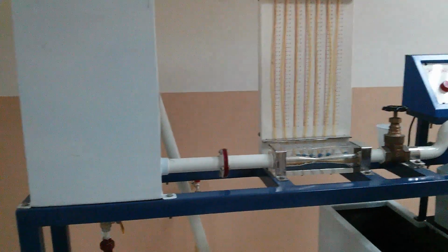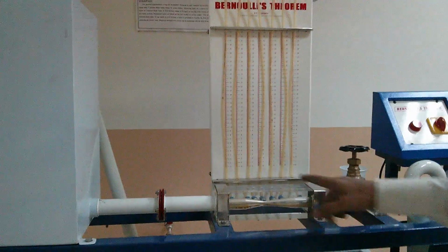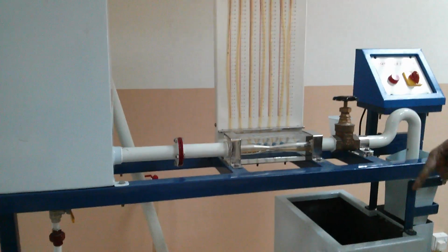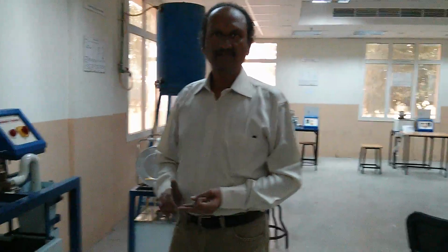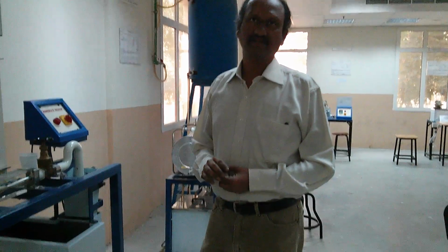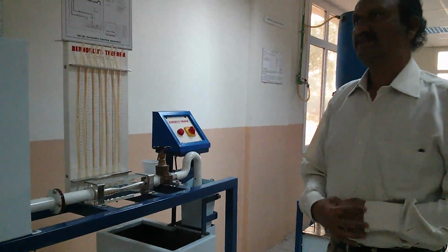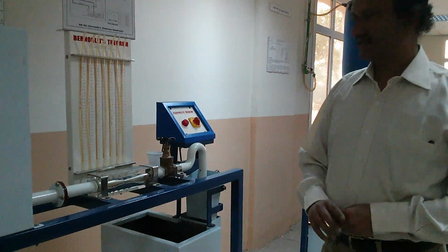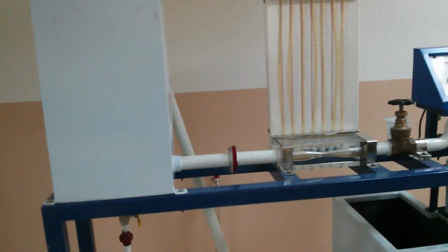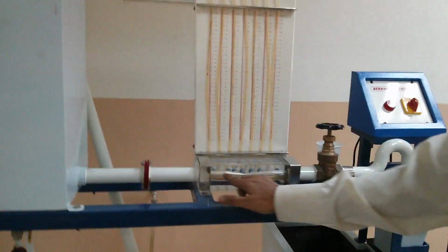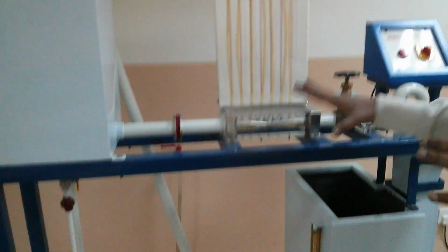Then with the help of the readings, finally you are required to draw a graph showing the length or the cross sections on the x-axis and the total energy. The total energy is, as you know, the summation of the pressure energy, velocity energy, and the potential energy, right? If the entire cross section is at the same level, the potential energy would be 0. The only thing is, you will be finding the velocity at different points, which means you will be finding the kinetic energy, and the pressure energy is obtained from the piezometer. So the sum of the pressure energy and the kinetic energy at each and every location, you are finding it. And finally you need to show that these values are almost the same, right?